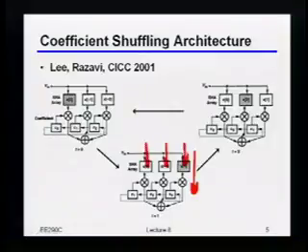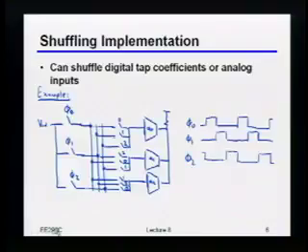Okay, so what really gets complicated is imagine you wanted to do this for 20 taps, or 40 taps, or 100 taps, right? Now I need 100 or 40 or 20 or whatever it is, different clock phases, right? And as you just said, this thing is going to become a big beast in terms of routing it everywhere and figuring out which wire goes where. And actually, in fact, if you see this picture, it'll make maybe even more sense because this is just an example of how you might implement this.